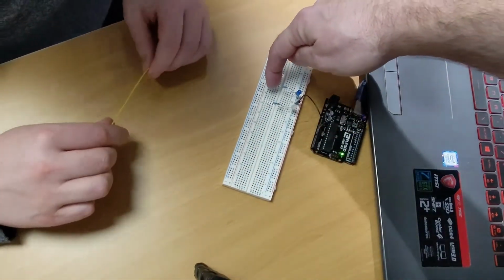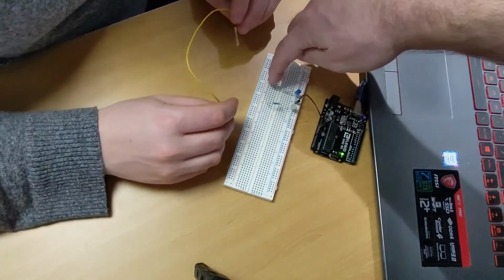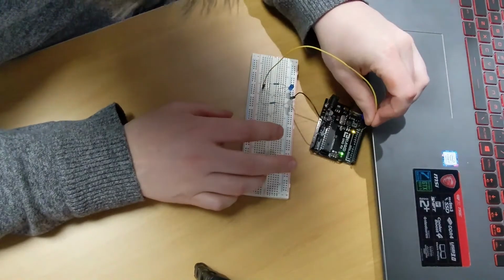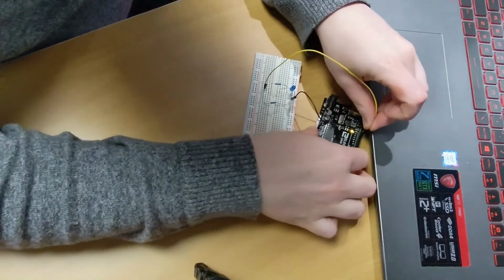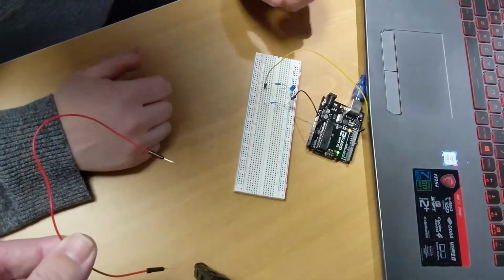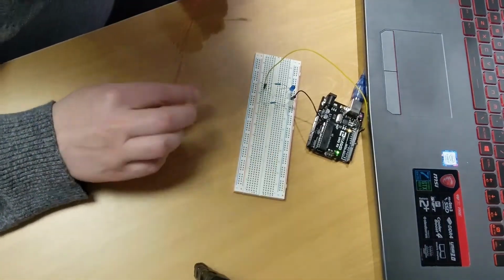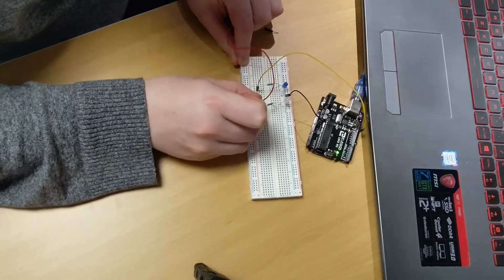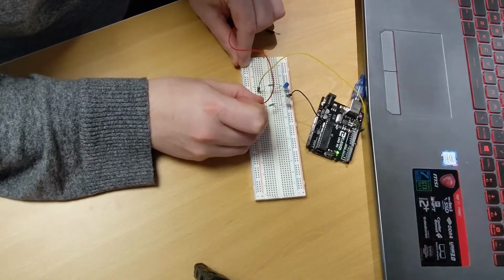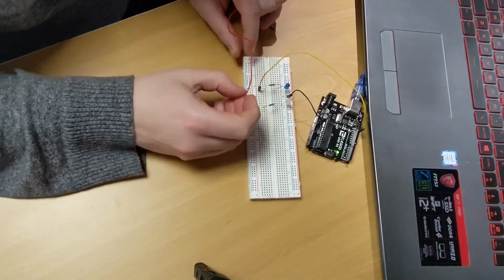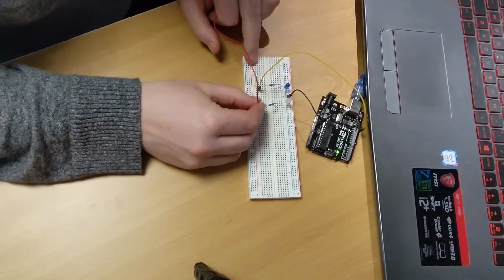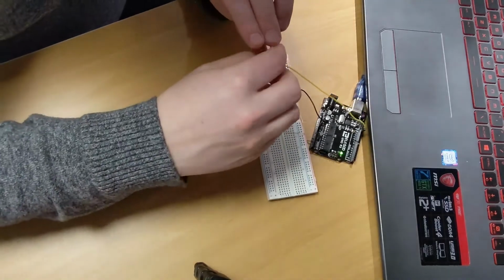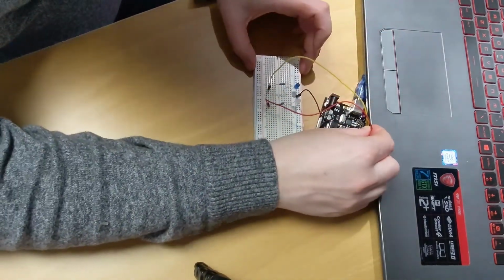So put the one back in from pin 13 to the end of that resistor. So let's get that one flashing again. This resistor goes into pin 13. Okay, so there's pin 13. And then put that one in for the other end of this resistor just here. You can pick basically whichever number you want, but you might as well go with pin number 12, which is right next to it. Sorry, it's a bit difficult to get that one. It is always a bit fiddly when you're first going with it. And we're going to go into pin number 12 here.